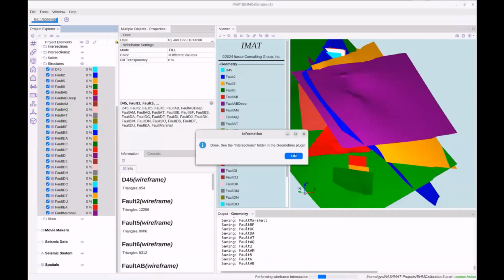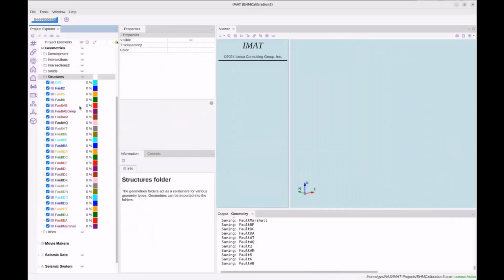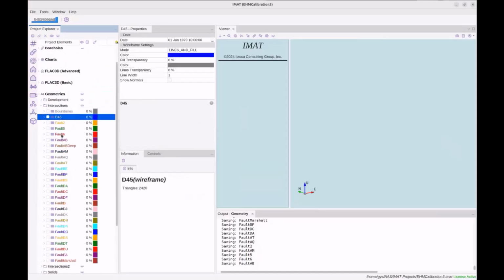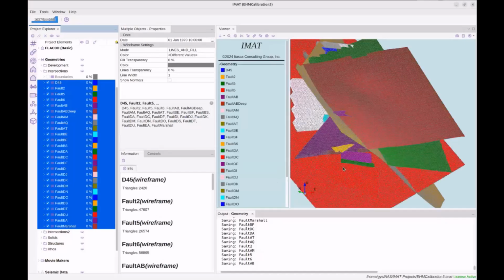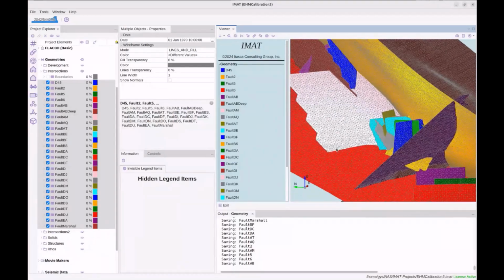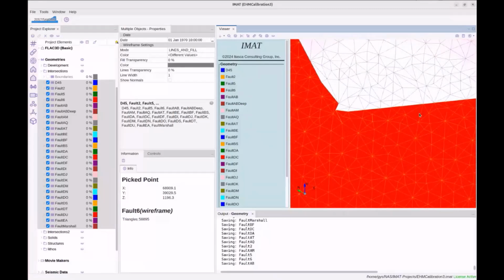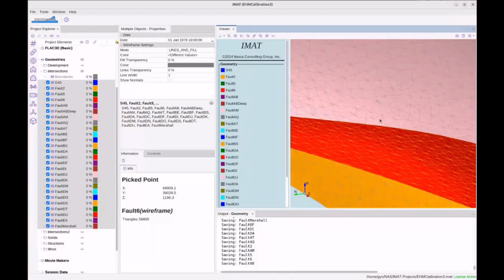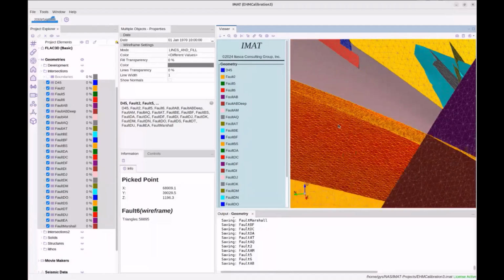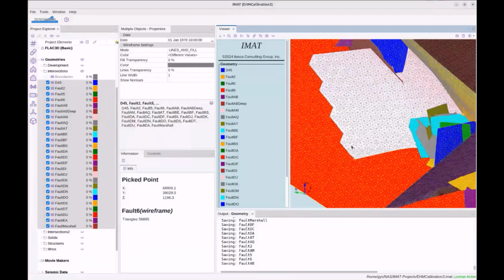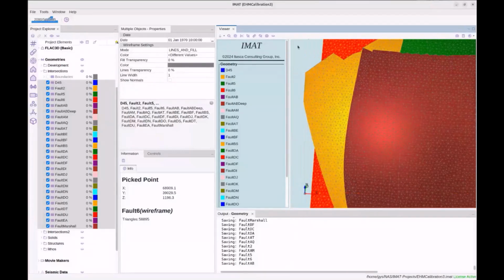So it's finished, and it says it's written out all the new geometries in the geometries plugin, and the intersections plugin. So here's all those intersections. It wrote out all the intersections for you. I'll just zoom in, and you can see these meshes are now triangulated. And if I look at the intersections, you'll see the intersection should theoretically be perfect. For example, this structure that previously intersected this structure over here is now properly terminated for you. So yeah, in most cases, this works quite well.